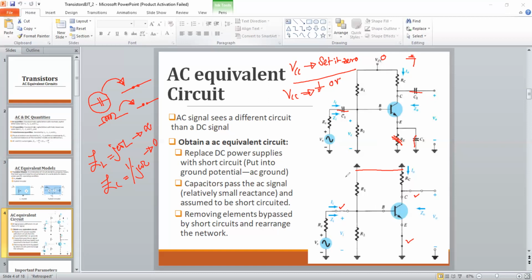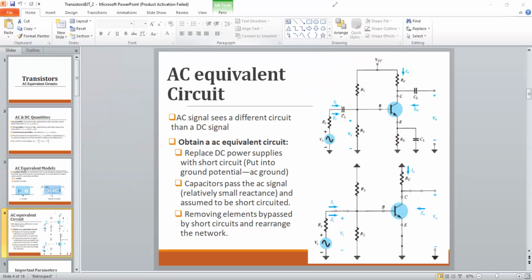Now what we can do here is think of simplifying it further. Now we have a transistor here. The emitter is simply grounded, so I'll just draw this one. This is already grounded. This is base and collector. What happens to the collector? It is basically grounded through RC. So the collector is simply grounded through RC. What's the output voltage, where we basically measure the output? It's between the collector and the ground. So this is your collector and this is your ground, and this becomes the V out.